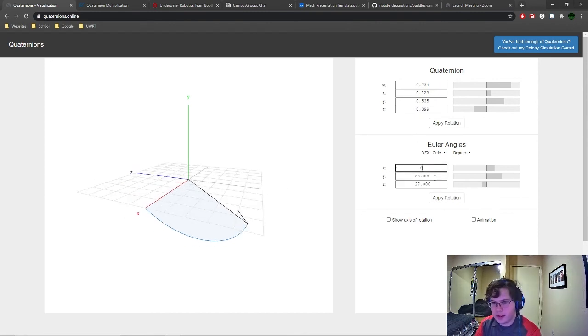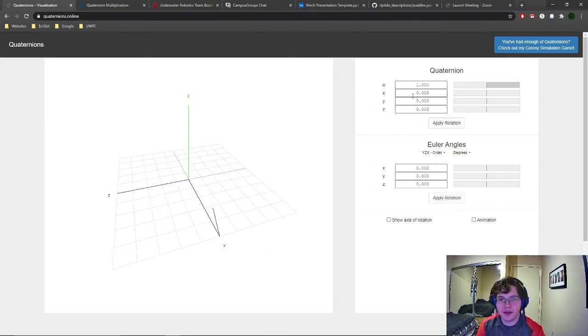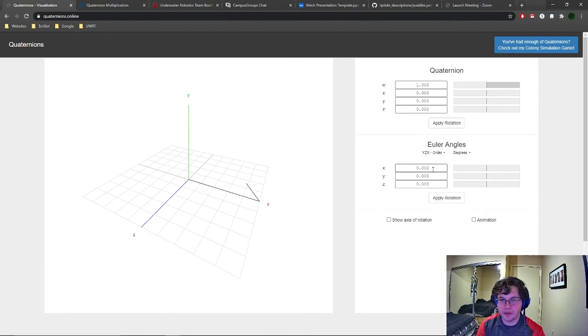Quaternions are definitely more difficult. The reason why they're useful for us is that the math on them is incredibly simple. With Euler angles, we reach some black hole areas where angles converge on each other. For example, here, if I go 90 degrees pitch, changing my y will change your roll, and then also changing your x will change your roll. And of course, that's not exactly what we want in our coordinate systems, where x and y do the same thing.